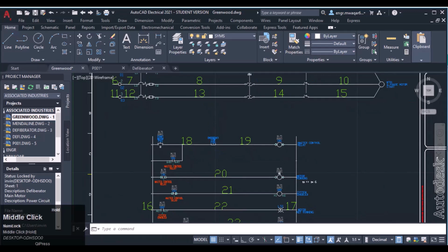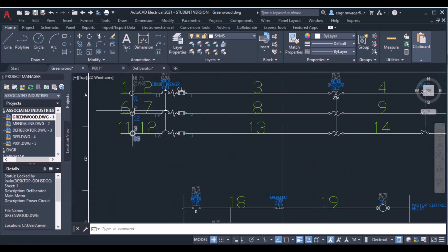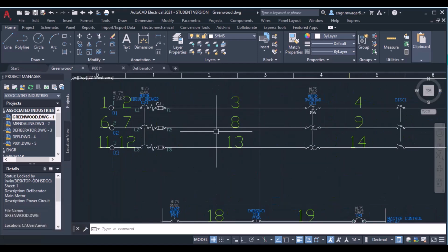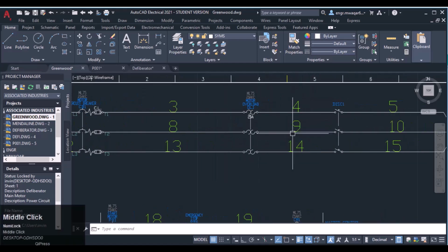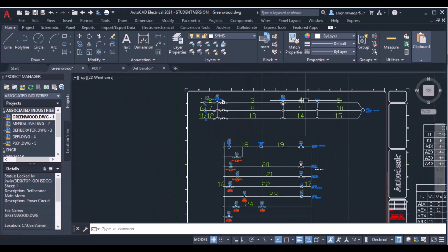In the previous lecture, we created these types of circuits and tables, and I entered 3 terminals, and the terminal which I selected was the terminal having different wire numbers at both ends of its terminal. So you can see the numbers at both ends of this terminal are different for these 3 ones. And between every 2 components, there is a different wire number. Actually, as you can see, it is the same line, but because of the different component placement between these drawings, its wire number must be changed.